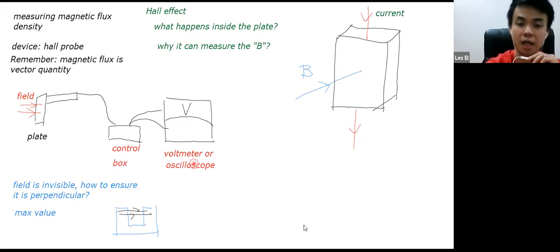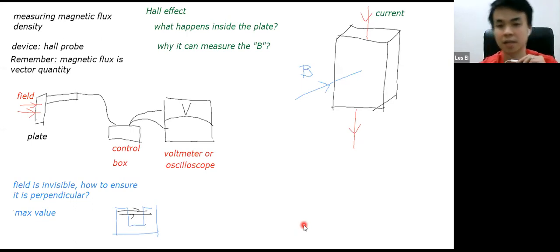In your report, if you write that you took several readings and found the average, that is not accepted. Taking several readings is a must, but in your steps you have to mention that you flip the probe. So you have to rotate it. Let's say your handle is at the right, then in your second experiment your handle must be at the left.